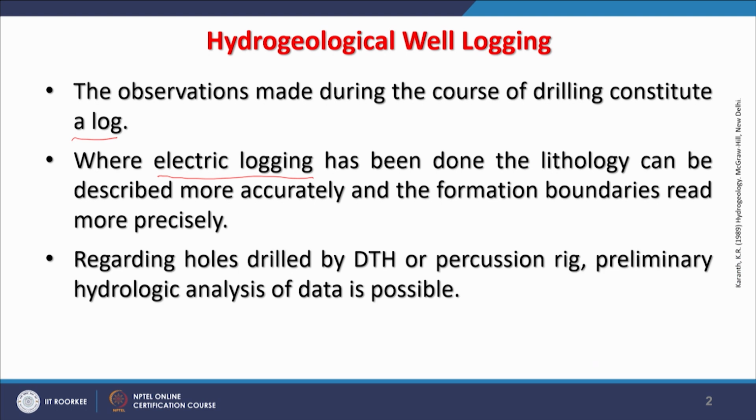If drilling is done by a down-the-hole hammer or percussion method, then some preliminary hydrologic analysis of the data is possible, because if the water coming out is analyzed geochemically, we get information about salinity, pH and other things. So it depends on what kind of drilling method. As mentioned, whatever is possible to record at that stage, everything should be recorded.